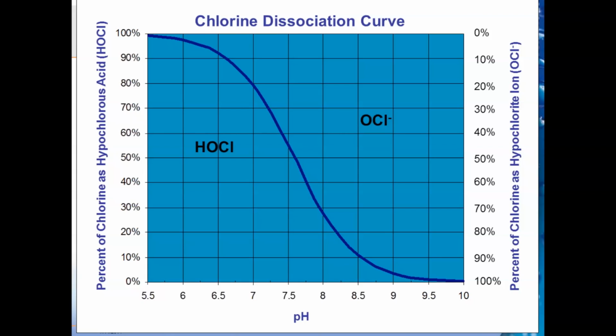And we'll talk more about this. The chlorine gas was acidic in nature, so it actually helped lower the pH of the process. So where we were at pH 8.5, it may lower it to 7.5. You can see that the HOCl is about 55% at 7.5, and the OCl minus would be 45% there. So it's much more effective. It's much more efficient for the disinfection strength.